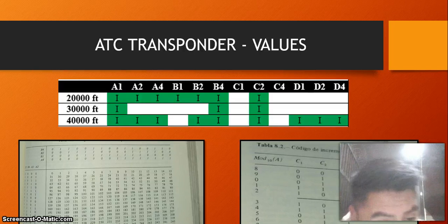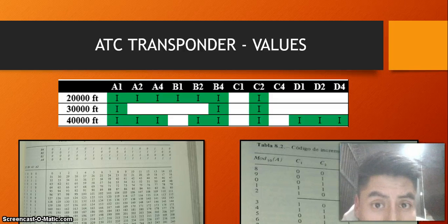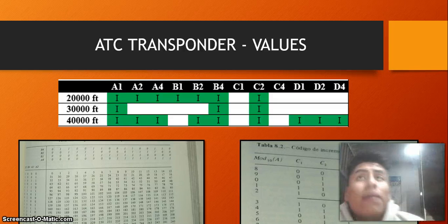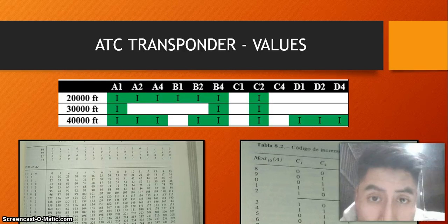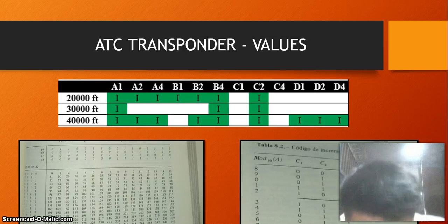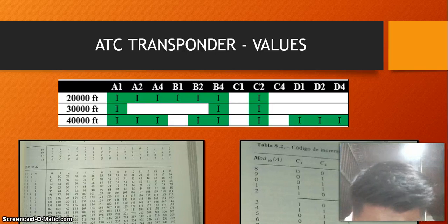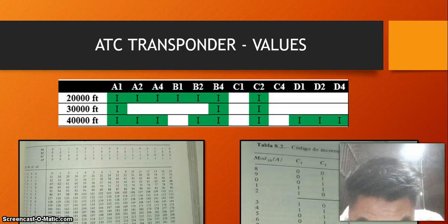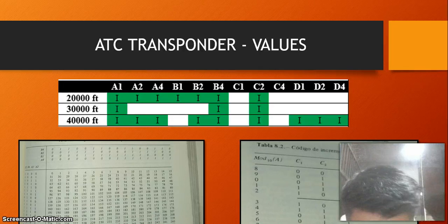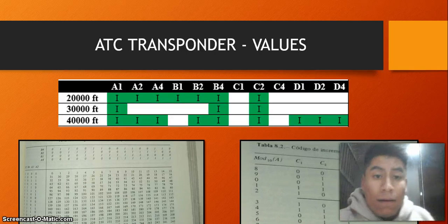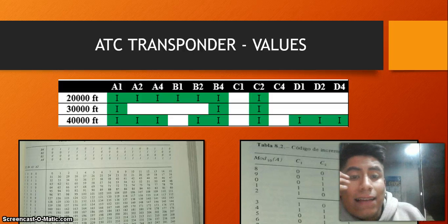You have two other control knobs, and this knob is used for the pulse signals at 1030 megahertz, and the response at 1090 megahertz. So that the received signal is even cleaner and more satisfactory, it adjusts the width of the signal.